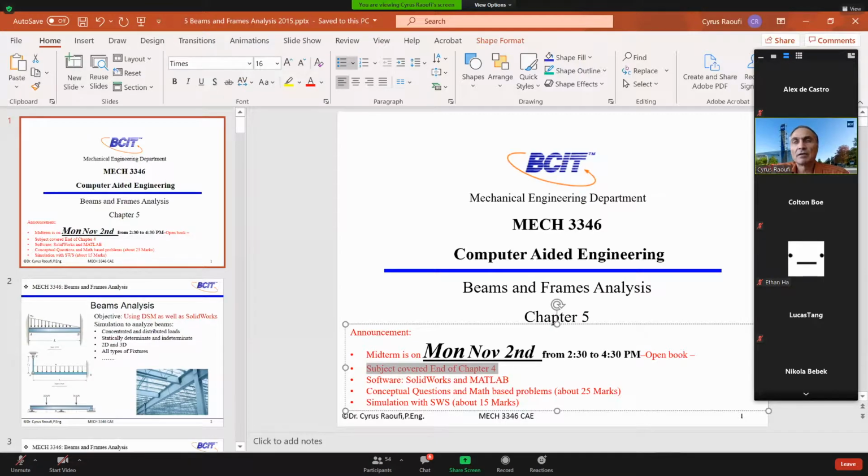Then we looked at the different types of meshing techniques in SolidWorks. That was a standard mesh with a mesh refinement, which is a standard approach. Then we looked at the standard mesh with automatic transition. Then we looked at the curve-based mesh.